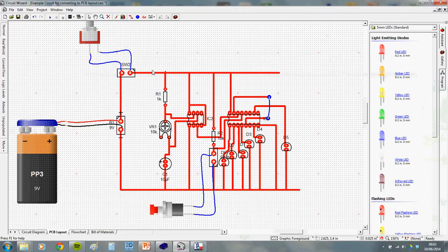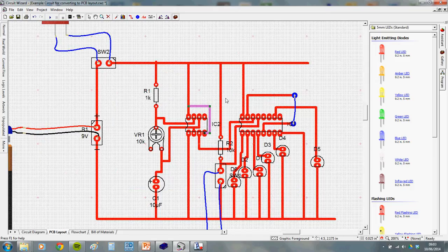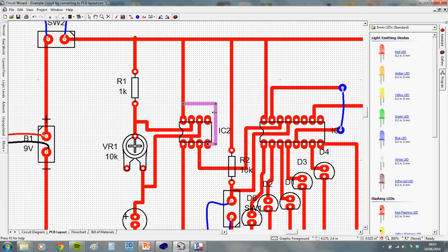Right, we could make it tinier in a lot of ways here. There is lots and lots of wasted space on this project board, and first of all, the reason we need to shrink it down. Firstly, it gets you more marks when you do your coursework because it shows you've been efficient with materials. Secondly, if you were actually manufacturing this, it would save you money. Every little bit less board you need is less copper material wasted, which means less money spent buying it. It means you can make more in one production run. Every flying wire you reduce means less soldering and drilling to do. So reducing and minimizing flying wires is what anyone manufacturing a PCB in real life would try to do. Anyway, we're going to try and compact this down.